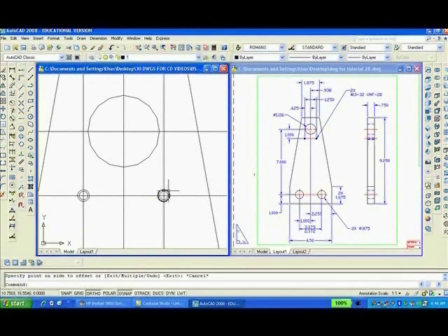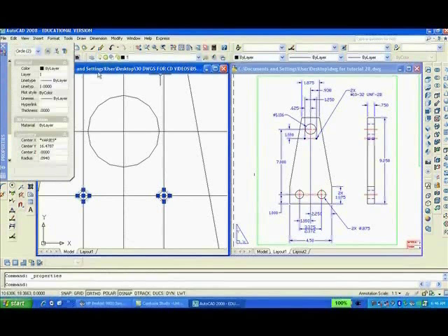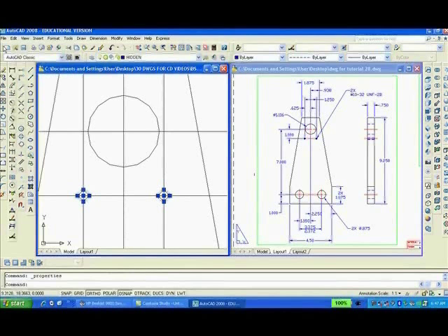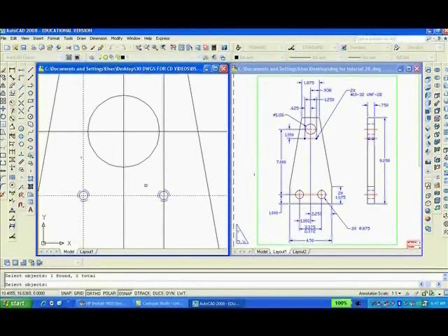I'm going to select the outside line there, and the outside circle there, and we're going to go to Properties, and switch it to a layer called Hidden. See what it looks like. Doesn't show very clearly, so I'll type LTS and make it 0.6. Perhaps that's better. And now we can erase the unnecessary construction lines again.